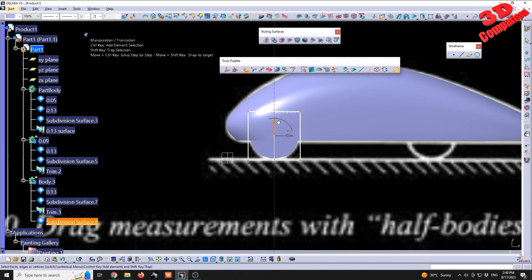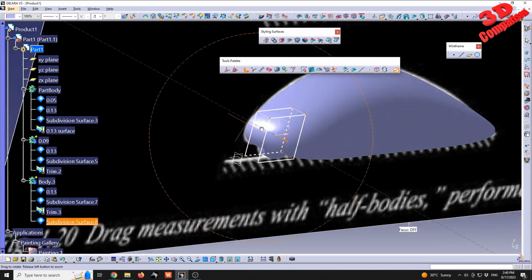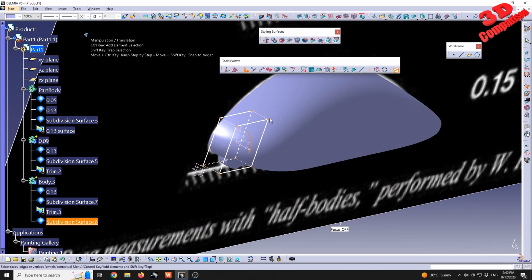So we're gonna see that this should be the location of that wheel. And a lot of people don't like imaginary shape because they don't have full control over the location of those shapes. But now we know that the width of the car is 1 meter 750. So we can just move this wheel, let's say half a meter into this direction.